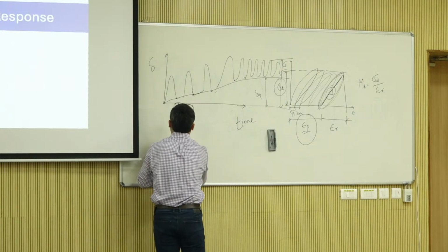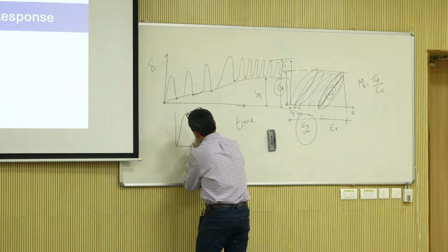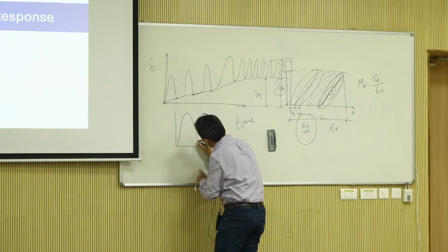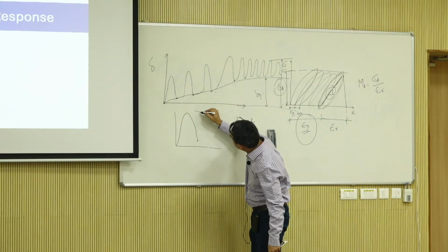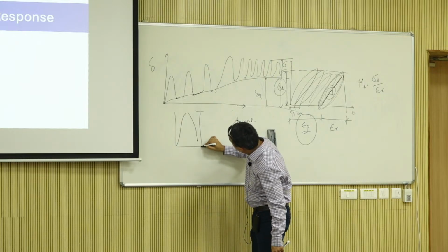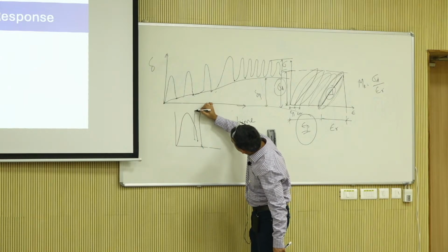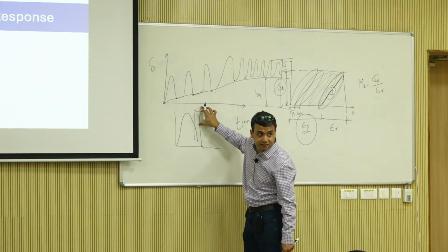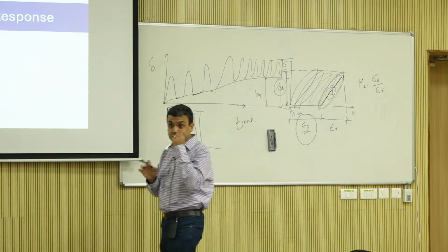So what you have to say is, if it started like this, did it come back to zero, or did it actually do something like this? Because if you just take total deformation, folks, you're going to divide by this whole amount, but you should actually be dividing it by this amount. Does that make sense, what I'm saying?